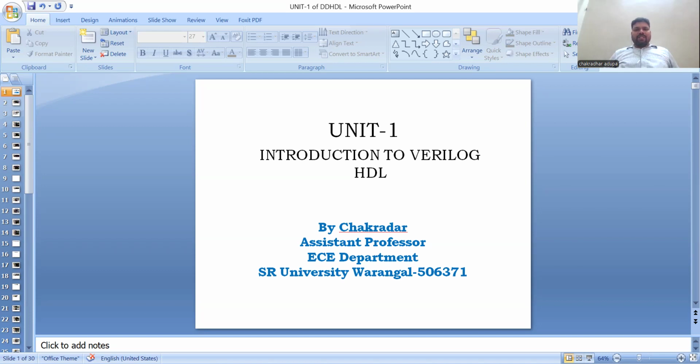Verilog HDL is a hardware description language used to model a digital system at many levels, ranging from the algorithmic level to the gate level and to the switch level. The complexity of the digital system being modeled could vary from that of a simple gate to a complete electronic digital system, or anything in between. The digital system can be described hierarchically, and timings can be explicitly modeled within the same description.